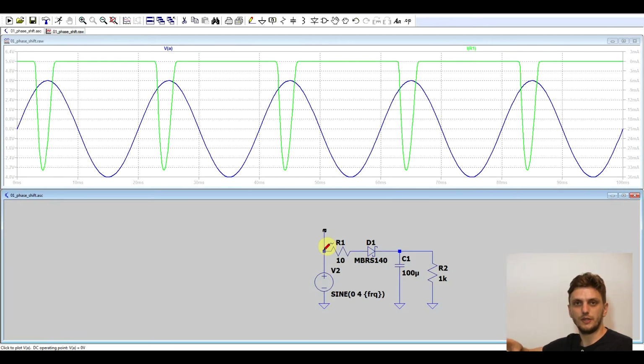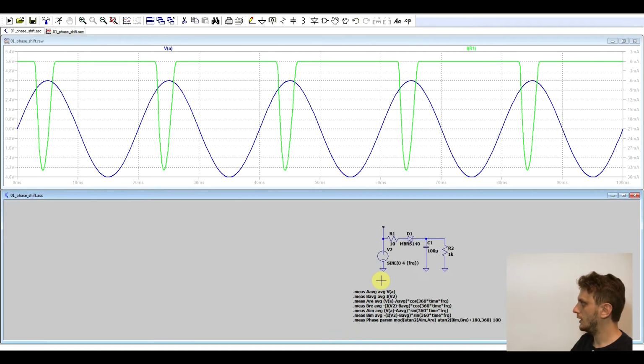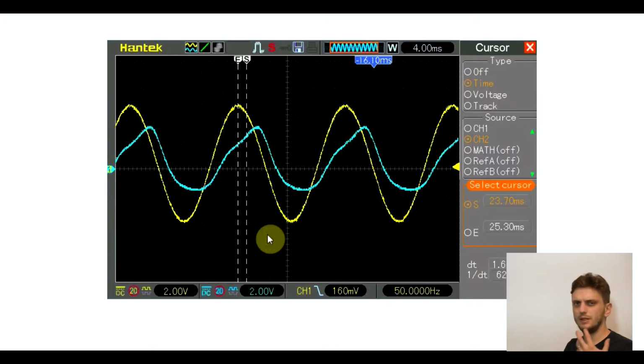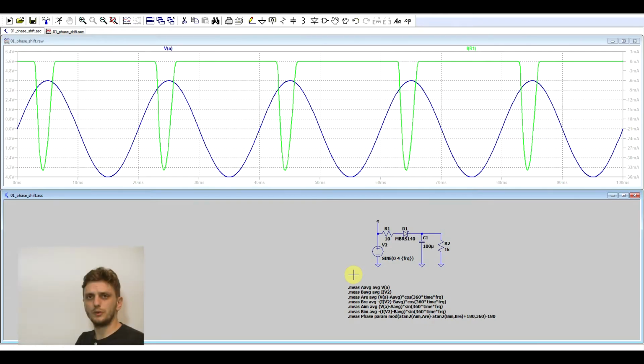So in this case the power factor also has to do with how efficiently we are pulling energy from the lines. Now we could again try to measure the phase shift by looking at the peaks of the waveforms, but in case of a more distorted waveform, so for example here I'm supplying a saturating inductor from my signal generator, we see that the peak of the current isn't really where it's supposed to be because of the way the waveform has been distorted. So a better way to extract the phase shift is to rely on a bit of complex mathematics.